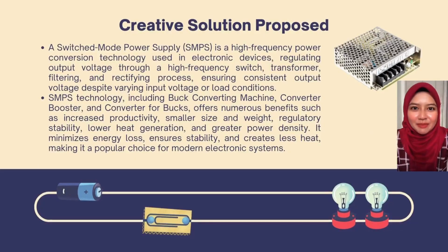A switch mode power supply (SMPS) is a sophisticated and efficient power conversion technology used in various electronic devices and applications. It operates by rapidly switching input voltage on and off at a higher frequency, unlike a standard linear power supply, which manages voltage by dissipating surplus energy as heat.